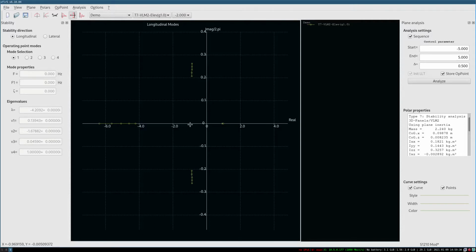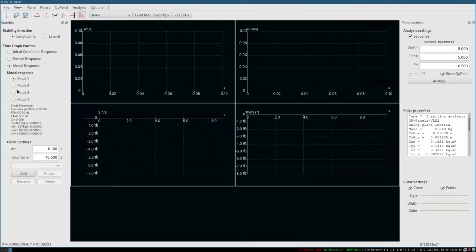i.e. I would not expect a timely response to the original flight conditions, but you could expect that a disturbance, for example, if a gust of wind under a wing induced a 15-degree bank angle, you would expect that bank angle to stay there for the time frame that is relevant to piloting this aircraft. And anything that is below -1 is going to be stable, so this stuff here is going to damp out relatively quickly.